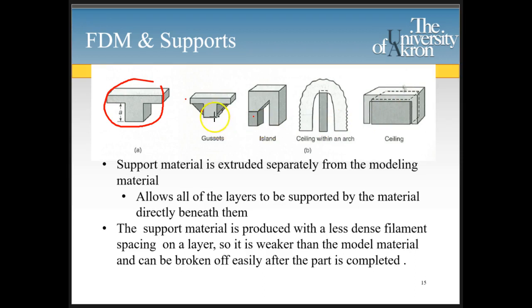Now, what's a way around this? You build it upside down. You put this end on the base, and then you fill this up. Now, the problem with that is you're still going to have some support material. You may not get as nice a surface finish as if you build it this way. Same thing with this one, I could just flip it over. Same thing with this, I could just flip it over. But the point is, when you design it, you have to think about it.